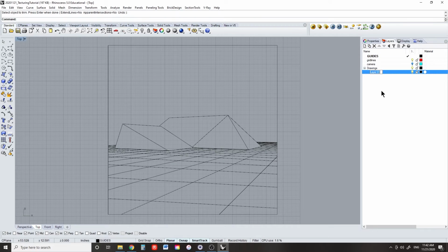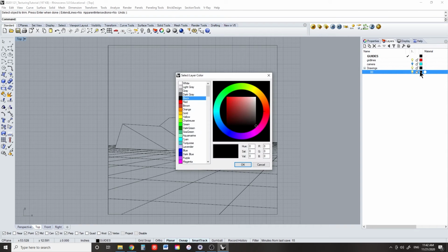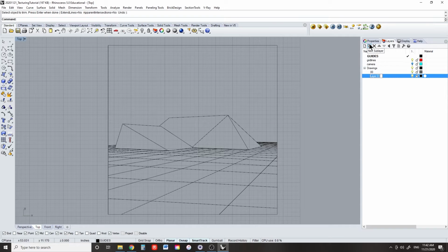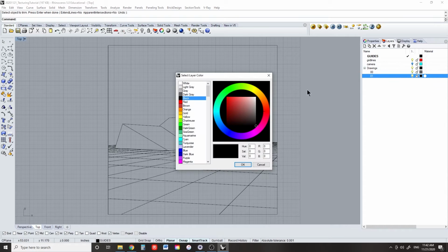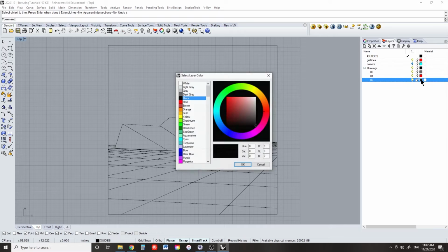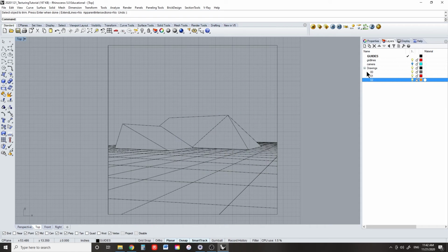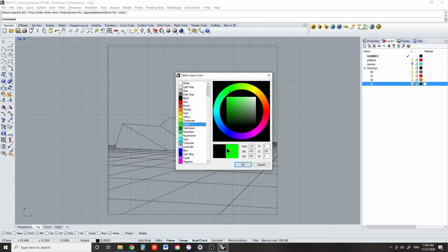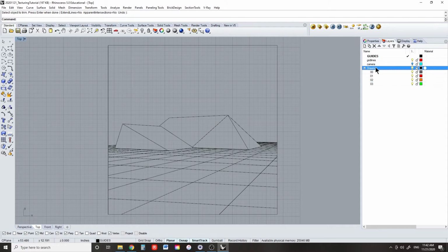Alright, now we're going to sort all of our line work into different layers so that we can give them different colors and different line weights. We're going to do this using sublayers. Select the drawings layer and then press New Sublayer. We're going to create a total of 8 sublayers, but we won't use them all. This is just good practice for a drawing template.